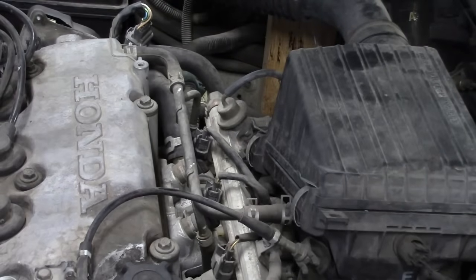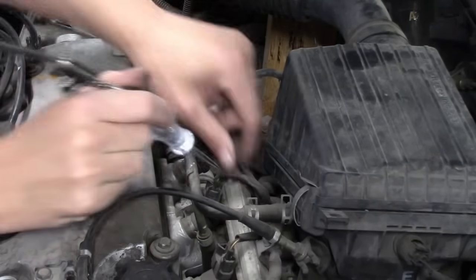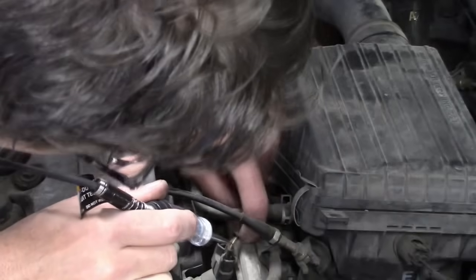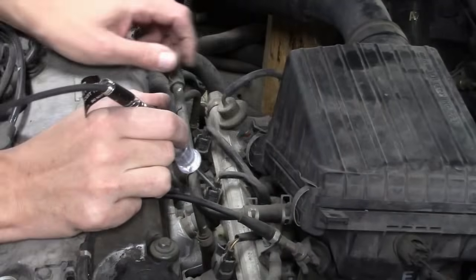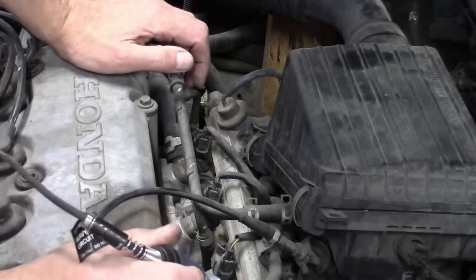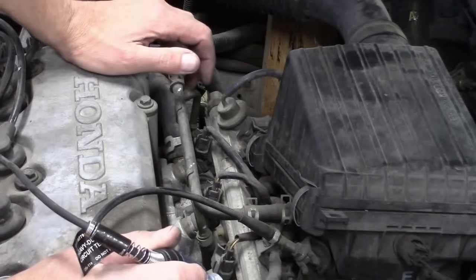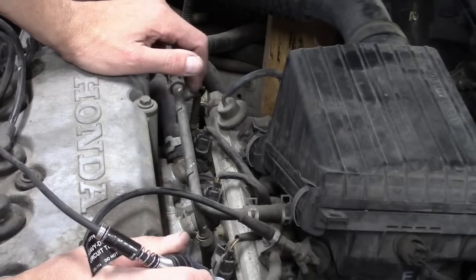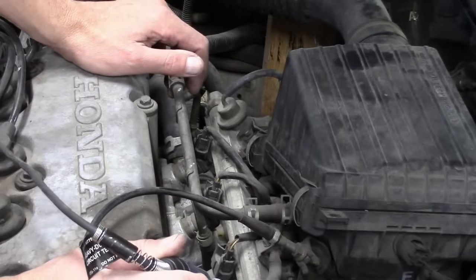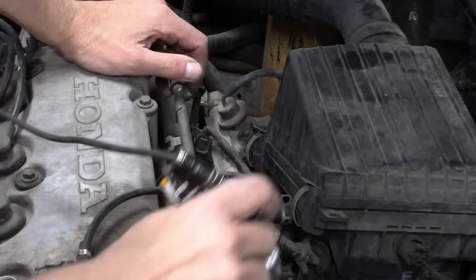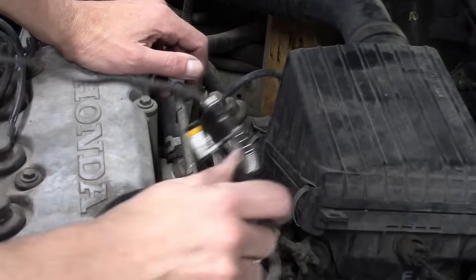All right, we've got all 4 fuel injectors in view here. And there is something that I can observe very easily here, and that is that each fuel injector, of course, has just 2 wires. It's going to have a power input and then a ground. And that ground, almost guaranteed, because I've never seen to the contrary, is going to be PCM controlled. So the way this works is you've got constant power to the injector.